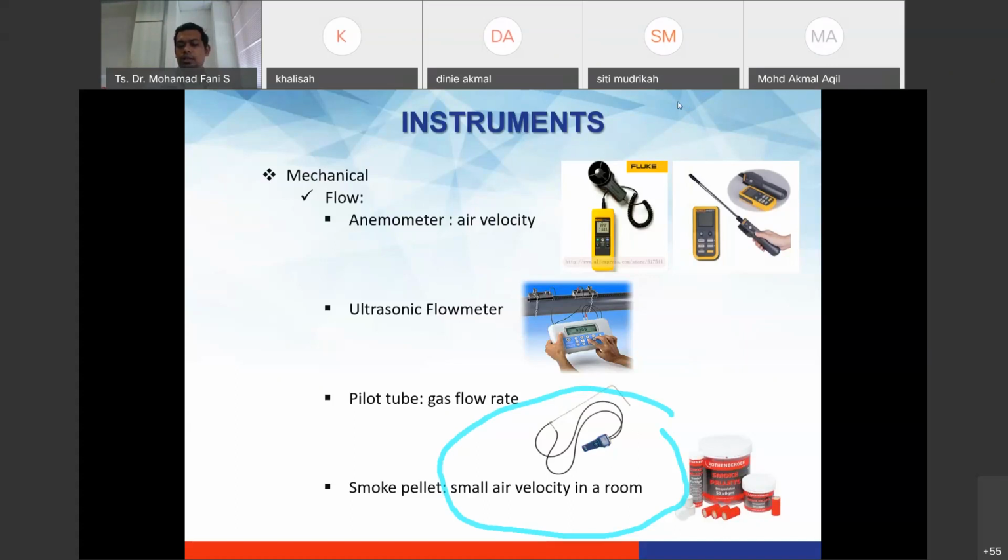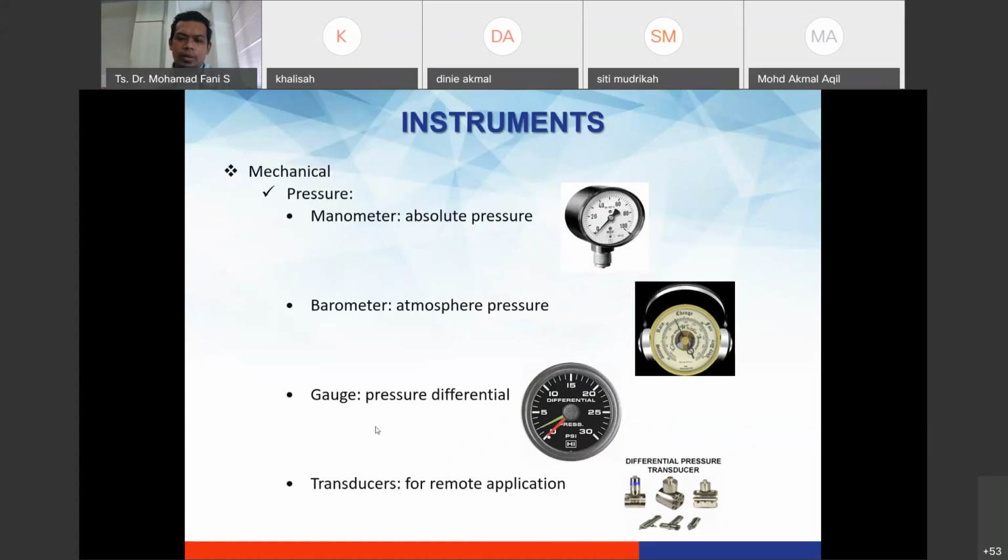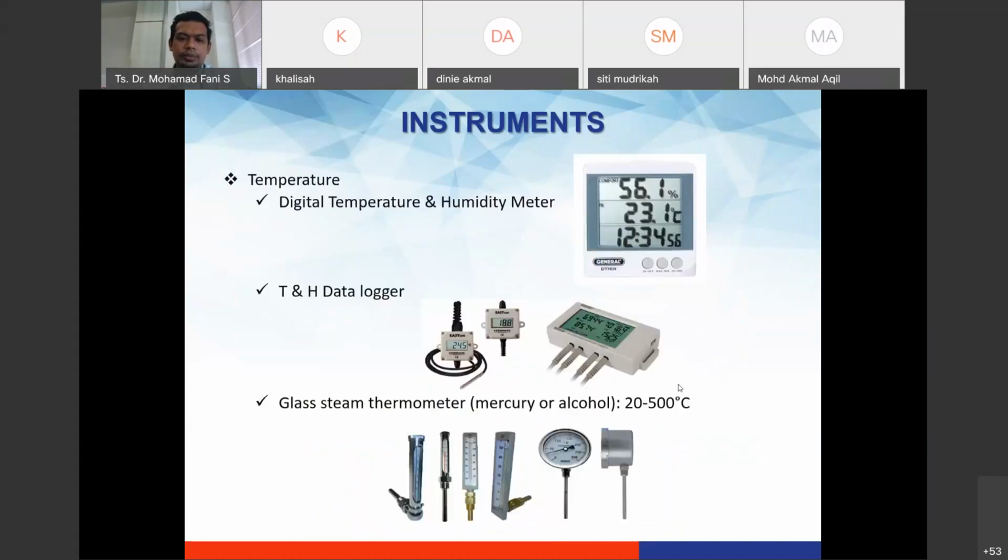The purpose of that is to ensure that the air flows inside the building in an efficient way and has a kind of balancing from the main supply to the end user. So if we get the same or very close value for the air velocity from the supply air, for example from the AHU to the end user, that is the efficient way of air supply by the system. All those meter gauges, okay, tachometer, can find. This one we can use inside the room.